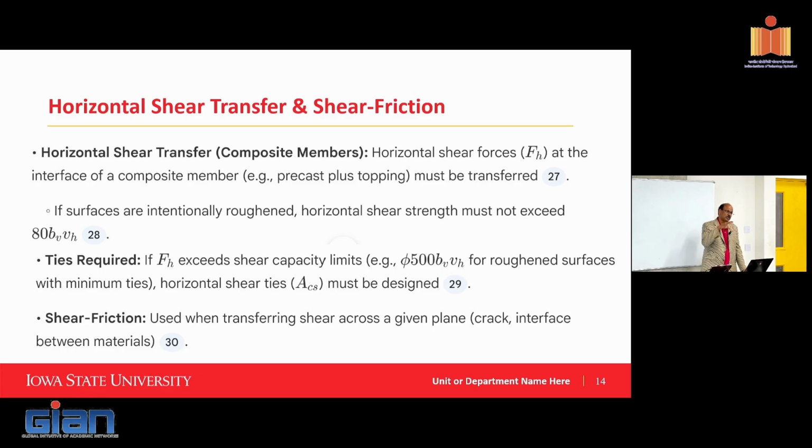When you do those supports, you have to make sure that shear can be transferred from one element to the other. Shear transfer requires some kind of mechanism, and you don't want to make it so complicated. So shear friction is relied upon quite a bit in terms of how much force you can transfer. Both ACI and PCI provide guidance in terms of how one should calculate.